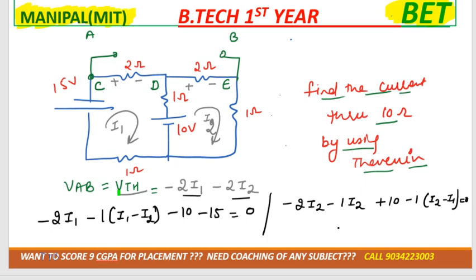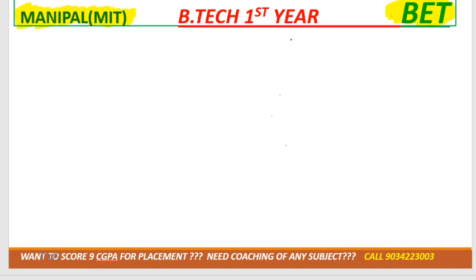If we solve these equations, wait a minute, here 1I1 was left out, minus 1I1 is also included in this term, right? So after solving, we'll get I1 equal to minus 6 ampere and I2 equal to 1 ampere. Got it? And if we substitute these values, we'll get 10 volt, or maybe minus 10 volt. Understood? Now after that, we need to calculate RTH.